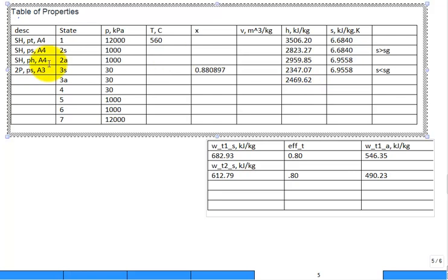All right, same thing. You come over here and you say, well, we know the pressure and the enthalpy. We conclude it's two-phase. You just do a little bit of work and you find that the quality did go up. The quality is now 0.93336, but it didn't have such high irreversibilities that it kicked it out into the superheated region.